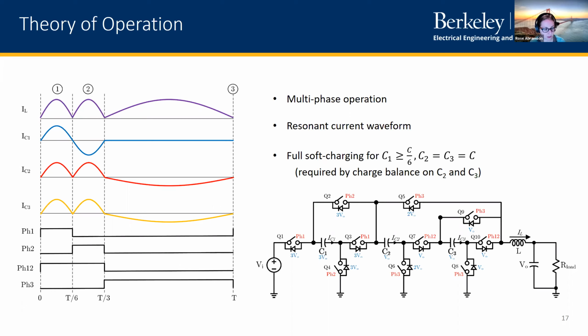You're just distributing it to maybe one server rack or one small subsection of that data center. So it's not running through the entire data center. They're designed to be very concentrated around that point of load. So the idea is that you would distribute at 48 volts as far as you can, and then once you're stepping down, you're stepping down right next to where the load is being consumed. So in terms of 8 volts being lower than 12 volts, that wouldn't be an issue.